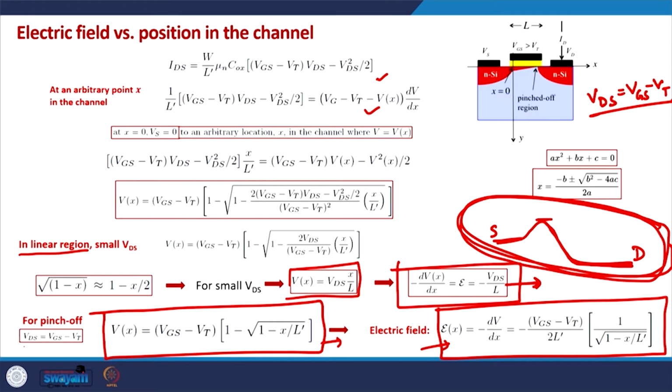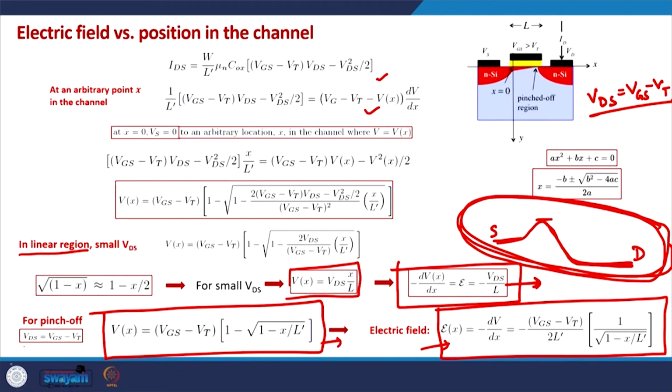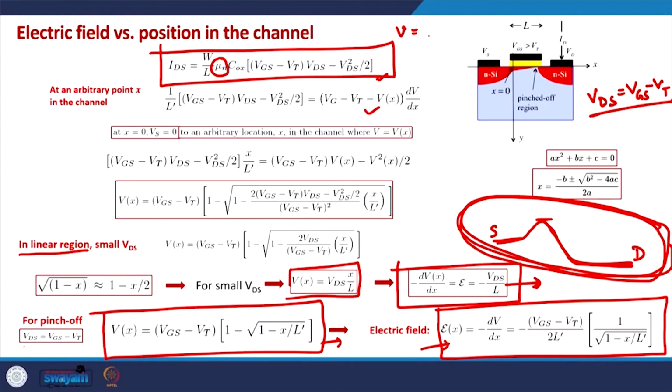So this essentially concludes our discussion of the classical or traditional approach of doing MOSFET electrostatics. But please remember that in this IV treatment of the MOSFET, we assume that the MOSFET is a long channel MOSFET, or at least not a ballistic MOSFET, because we are using the notion of mobility, the notion that velocity depends on the mobility and the electric field.